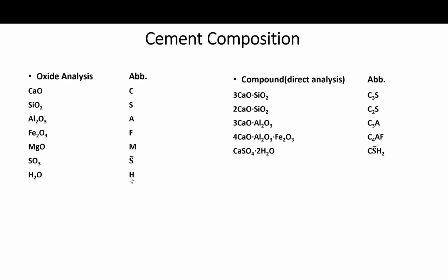So it is common practice in the cement industry to compute the compound composition of Portland cement from the oxide analysis by using a set of equations which were originally developed by Mr. Bogue long ago, and they still work. But again, eventually, the intent is to know the compound composition shown here.